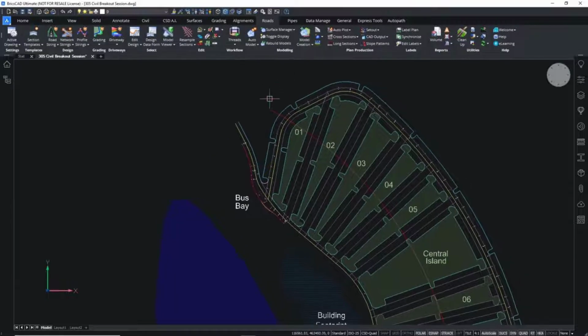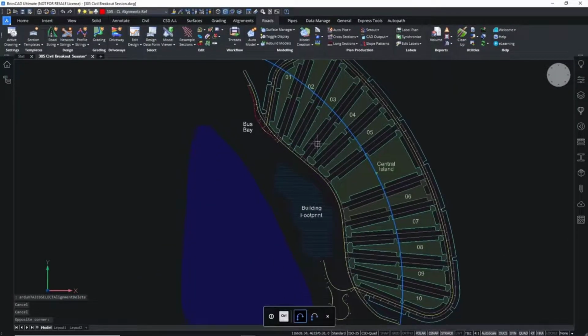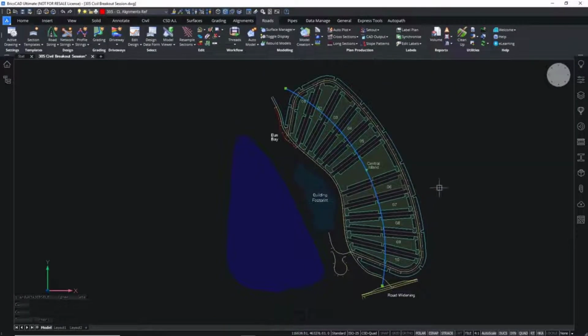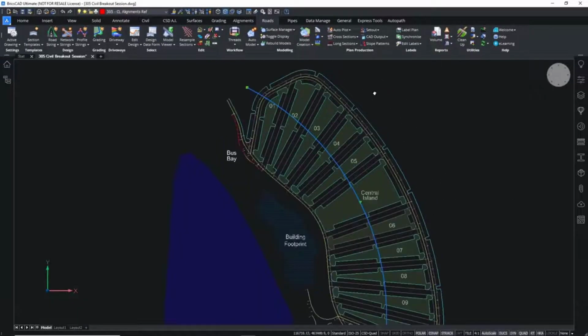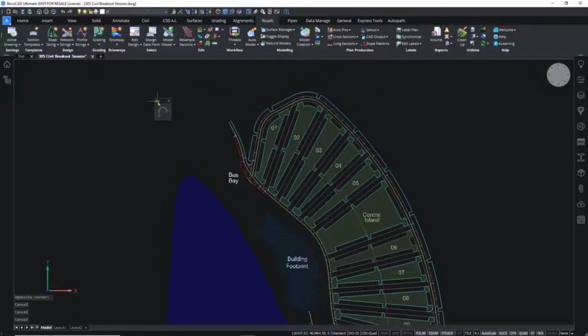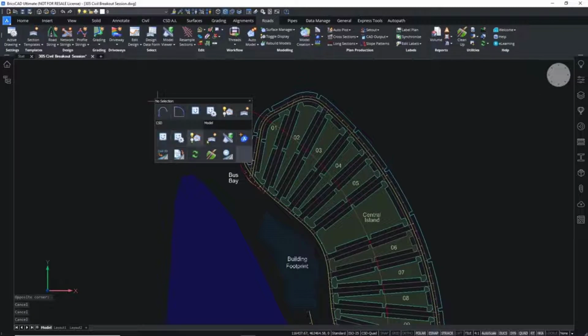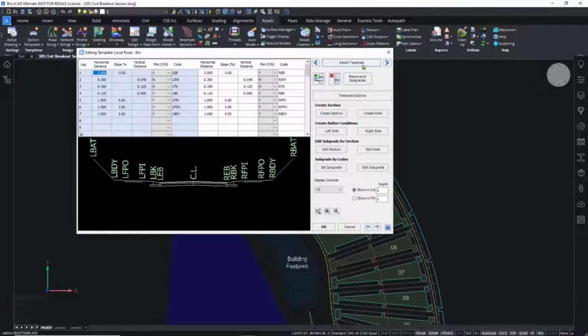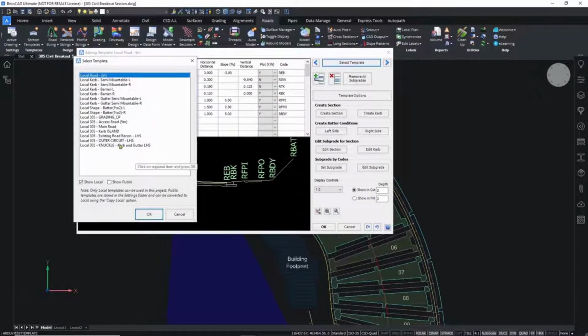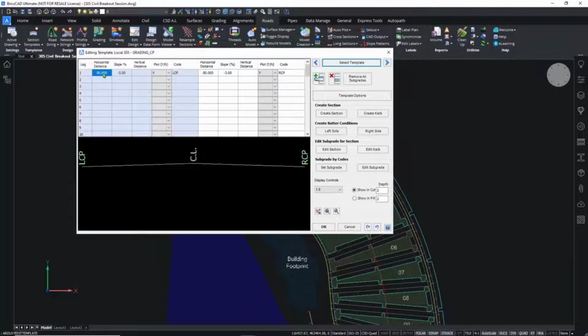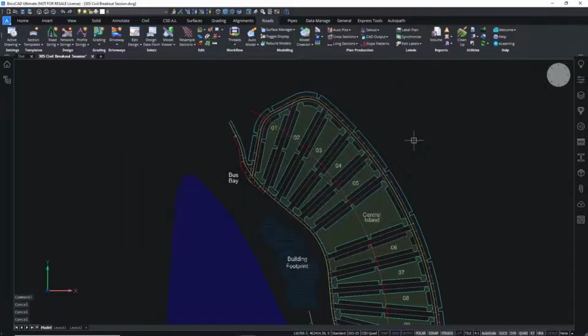We've got lots to do. We've got a polygon running down through our car park, which we'll use for the concept of our grading object. We have also got some templates created, which we mentioned earlier. One of these templates is a grading car park. That goes 80 meters left and 80 meters right at a slope of -3. When you do grading objects, they can have multiple facets to them, which we'll explain in a second.